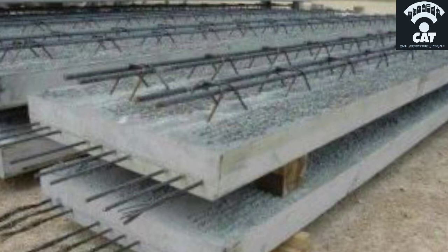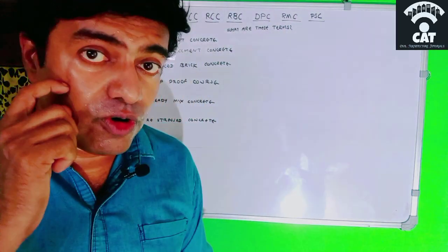Usually we buy steel from the market, let's say 450 or 500 yield stress. This steel can extend, and thereby we can provide the required amount of tension into the steel before concreting itself, so that we don't need much steel in that member. Otherwise, if we have to provide 5 or 6 steel members, we need to provide only one. That much is the difference between the pre-stressed member and the usual reinforced structure that we are using now.